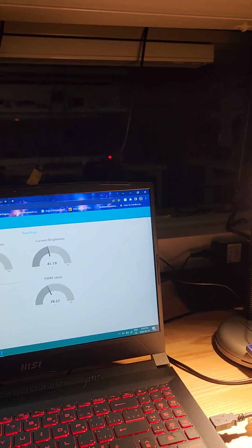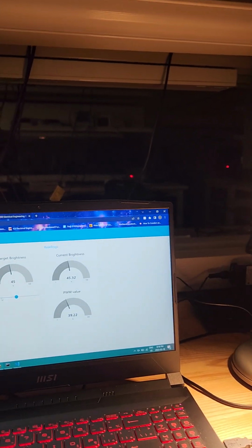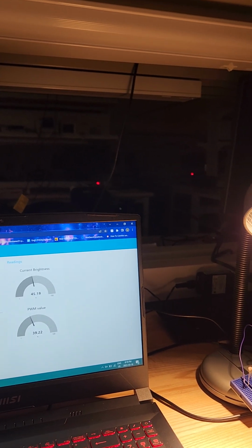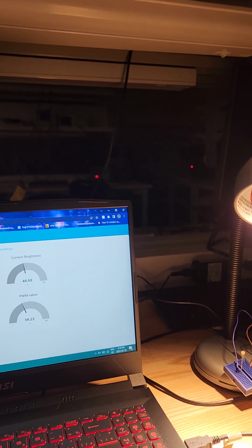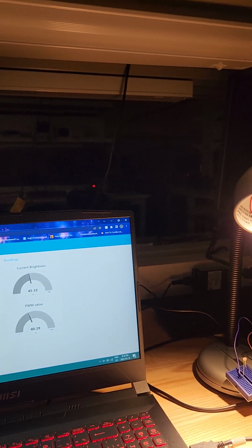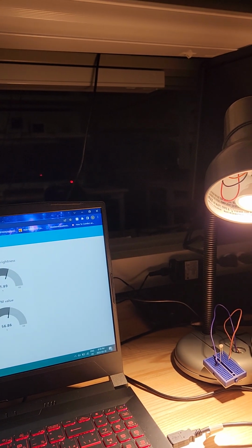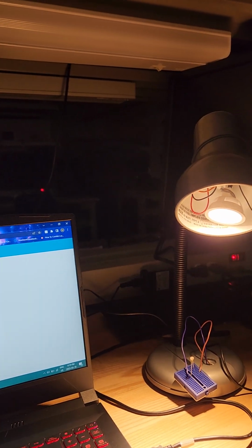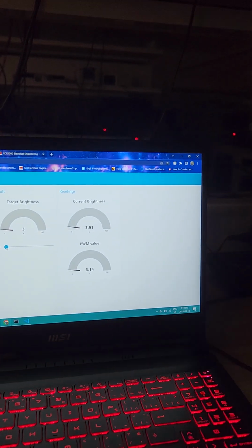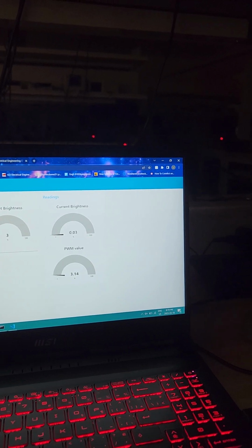In previous instances of this project, there was an issue encountered at low values of target brightness, where the dimmest setting of the lamp would be too bright for the target, and the lamp turned off would be too dark. This has been circumvented now, so in situations like this, where the target brightness is very low, the system is going to start lowering the brightness. Once it gets to that point, it's going to recognize that its lowest brightness is going to be too bright, and it's just going to keep the lamp off.